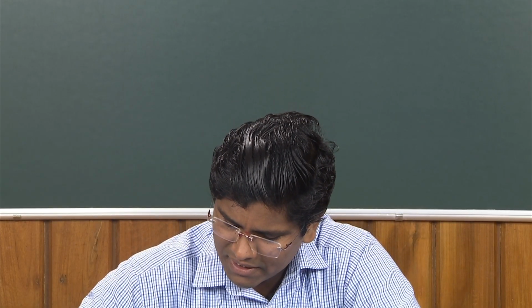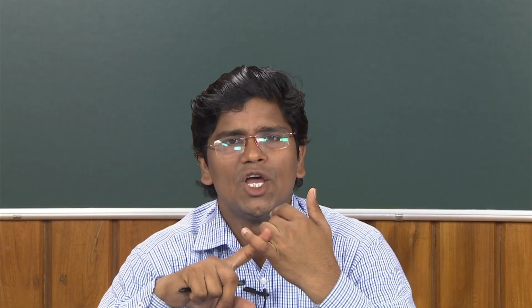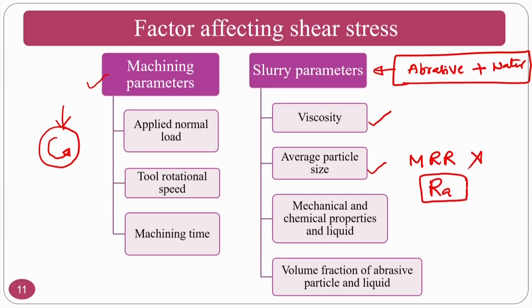Abrasive size of the particle: if you want to get a good surface finish, then you have to go for superfine or ultra fine particles. If material removal is the criterion, then you can go for coarser size particles. Normally, this particular process is used for the finishing of lenses. So in that circumstance, material removal may not be a criterion. The consideration is the surface roughness and figure accuracy and other things.